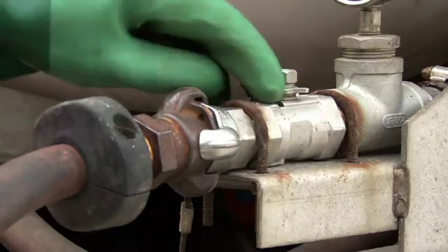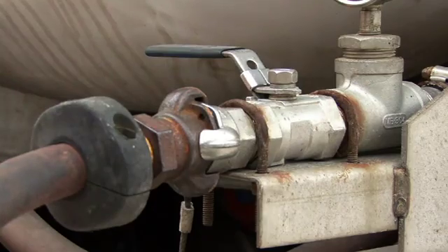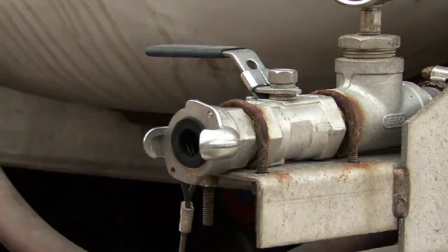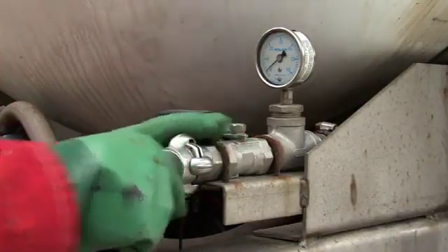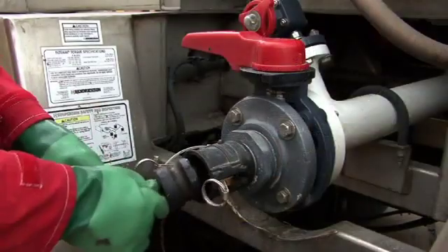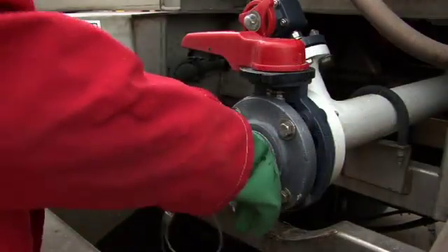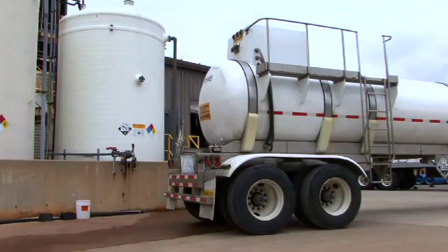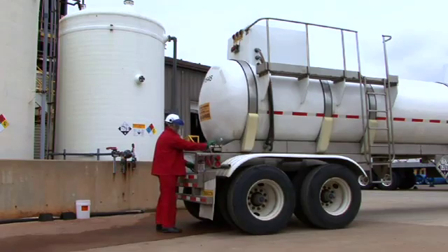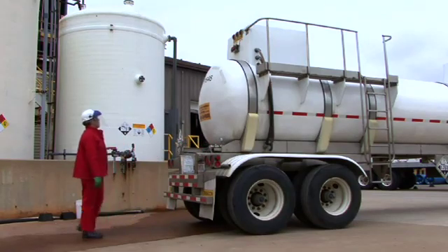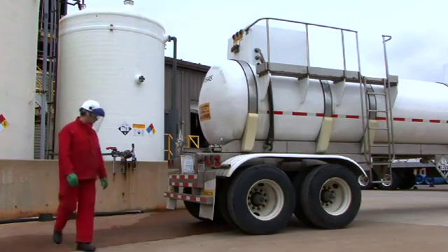Check the tank truck's internal pressure and relieve as necessary. Use caution when venting to prevent mist or spray of product. Secure the tank truck or other shipping container for shipment by installing plugs or caps on all openings. Attach all necessary placards and ensure paperwork is completed in accordance with DOT and other applicable regulations. Perform a final inspection prior to shipping.